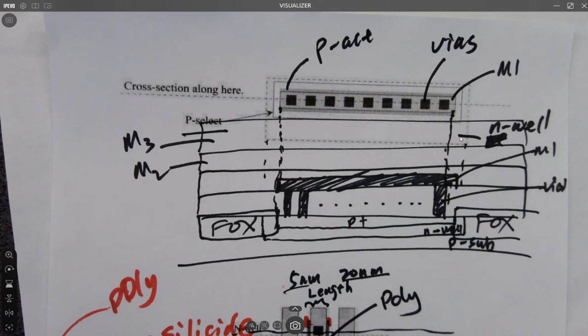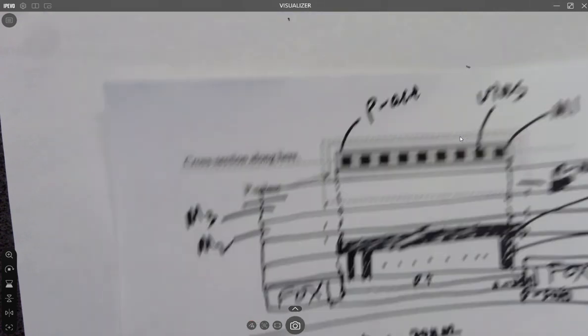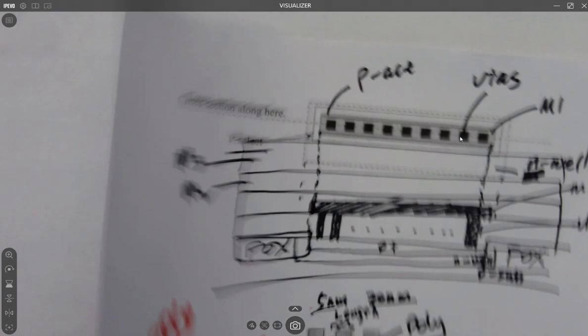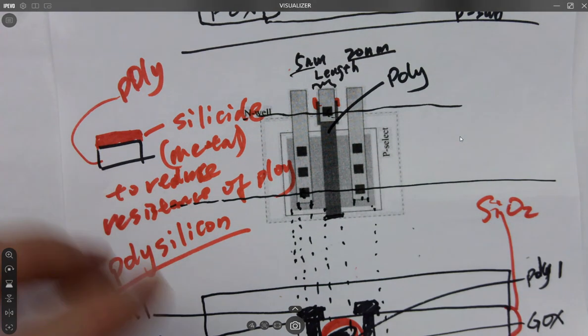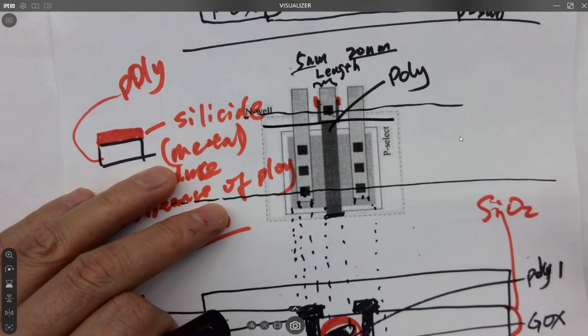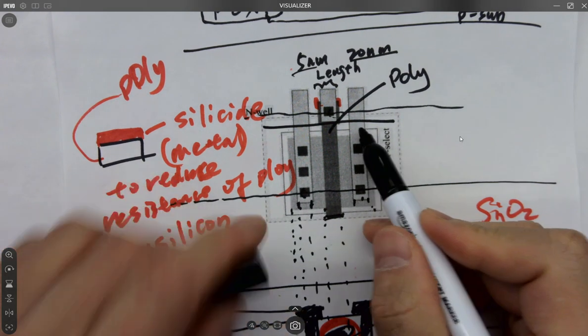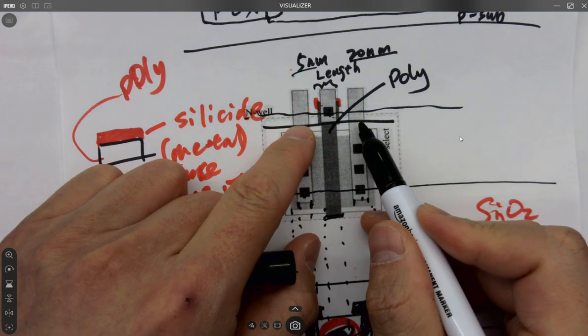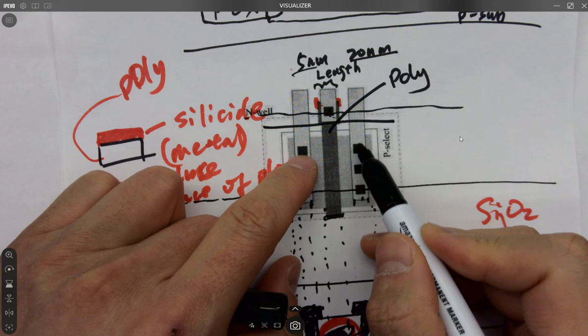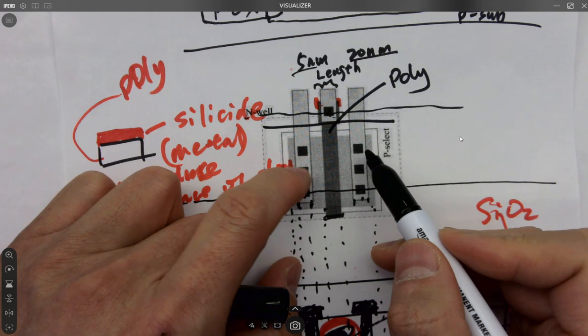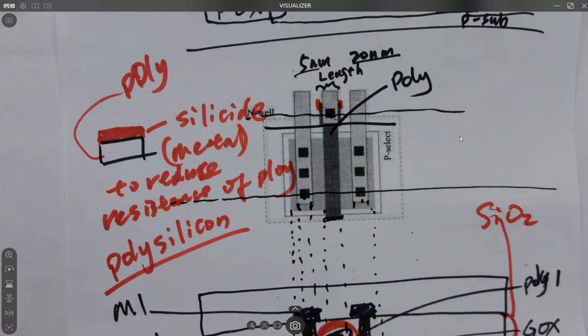There must be vias somewhere, right? If I draw a wire here, these metal ones don't have a via, but they must have via somewhere else in order to be meaningful. If it's just an insulated metal in the middle of the layer, why do we have to use it? It's going to be like an island.